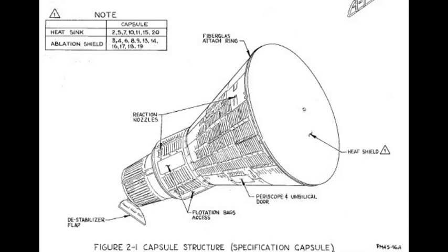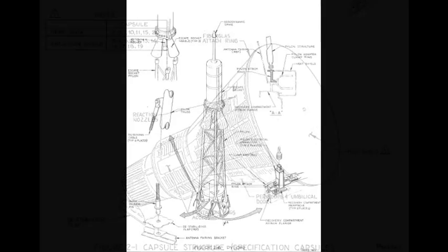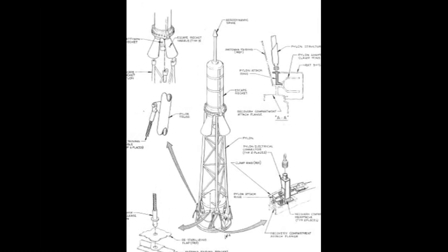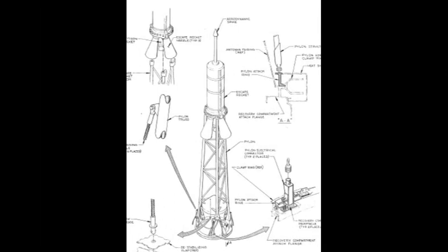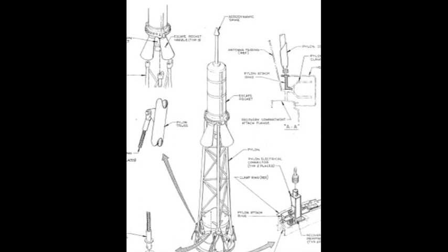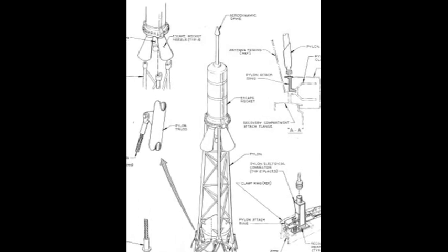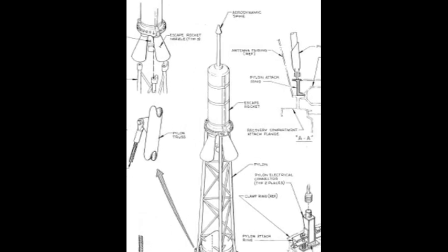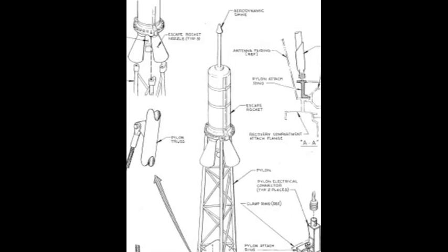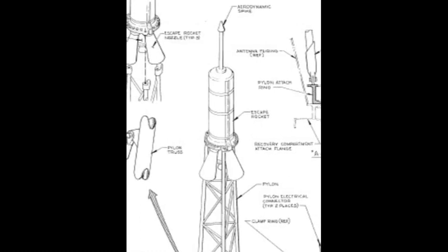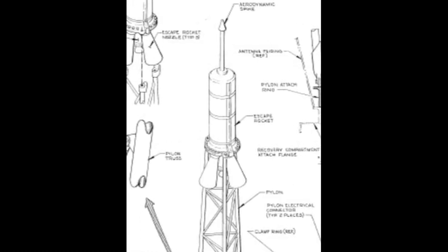2.2. Prior to capsule flight, an escape tower and antenna fairing are attached to the capsule afterbody cylindrical section. The escape tower, designed to aid in capsule missile emergency separation, consists of a pylon framework equipped with rockets. The antenna fairing is a cylindrical-shaped structure containing the capsule radio main receiving and transmitting antenna. The escape tower is jettisoned during the capsule launch phase or after an escape sequence. During the capsule landing phase, the antenna fairing is ejected and serves to deploy the capsule main chute.